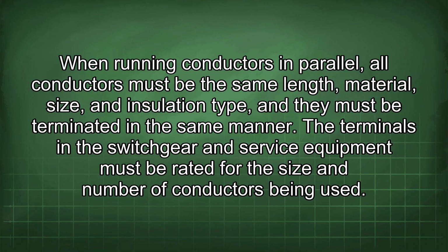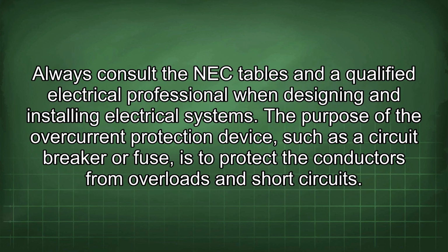When running conductors in parallel, all conductors must be the same length, material, size, and insulation type, and they must be terminated in the same manner. The terminals in the switchgear and service equipment must be rated for the size and number of conductors being used. Always consult the NEC tables and a qualified electrical professional when designing and installing electrical systems.